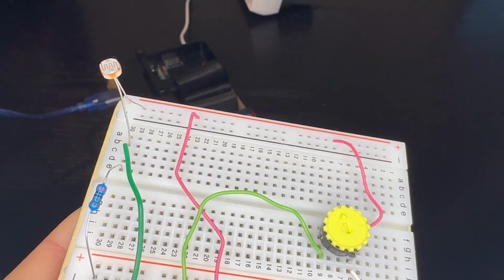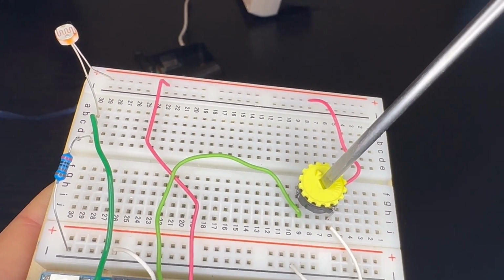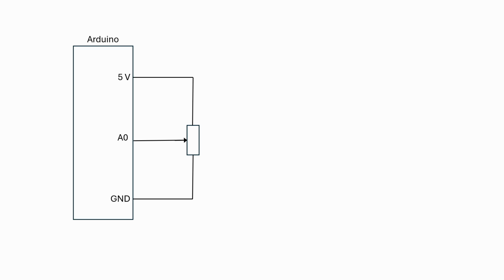from the Arduino. To the Arduino board, I have connected this LDR and a normal potentiometer. The potentiometer is connected to A0, the first analog input pin on the Arduino, and the LDR is connected to A1. That input is taken from the middle of a voltage divider using a 2 kilo ohms resistor.